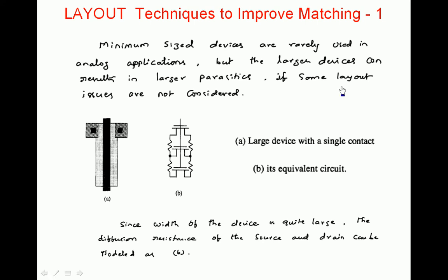A large length implies that the width also has to be very large, because W by L is the basic transistor, and whenever we increase the output reference current, W is going to be multiples of the current. So length is large, W is large, and W is multiplied by some integer, which makes it very, very large.